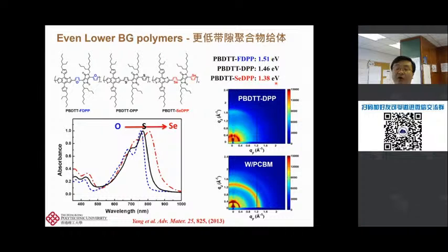Okay. And why this one is important is that if you think about tandem inorganic semiconductors, you can have one subcell at a 1.4 eV band gap. So that opens a broad view that you can do many things. In fact, we also use this one to go for tandem polymer solar cells, which will not be talked about here. Also note that this polymer has the so-called face-on orientation, similar to the second generation.